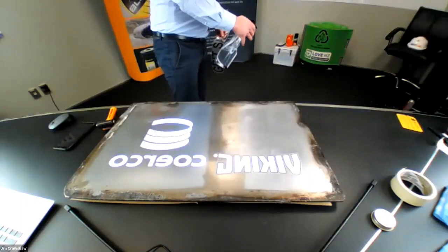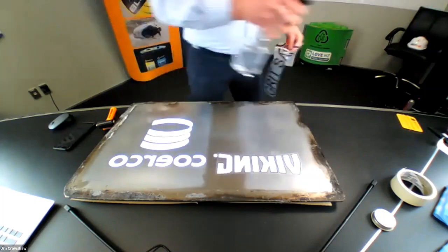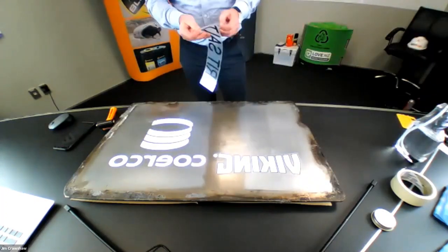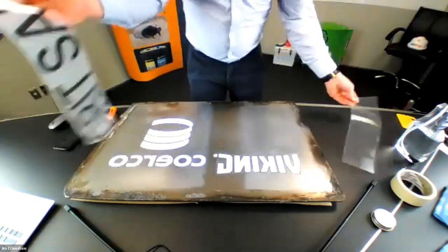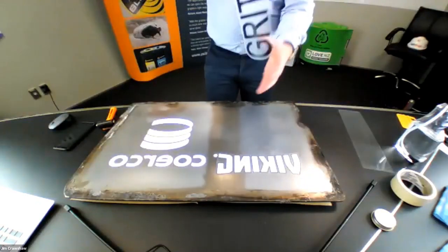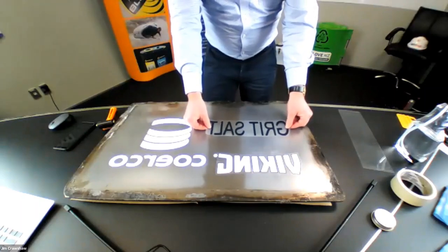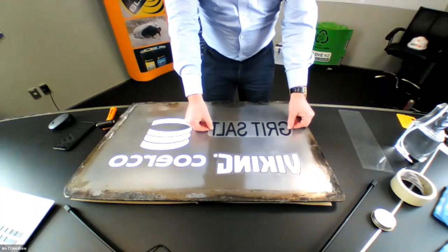So just make sure it's spraying. You spray a really light mist onto your mold like this here. And we're not talking much. And then peeling the graphic off the transfer, and then applying it onto the mold. And you can see here it's slipping around, so the adhesive isn't causing it to stay in one place. And that allows you to align it just perfectly.